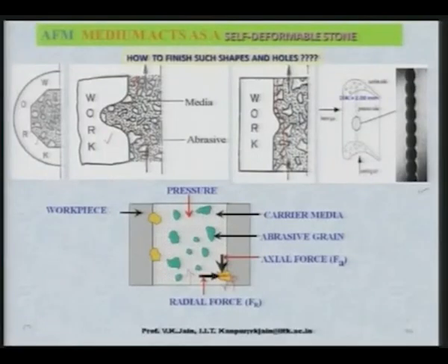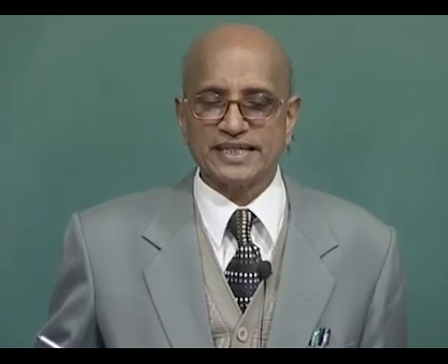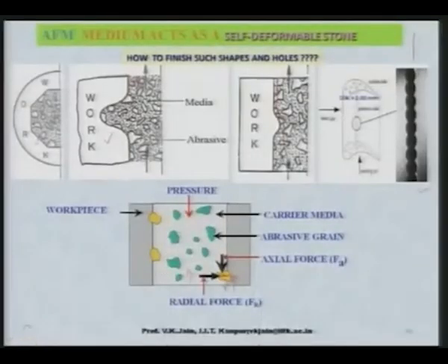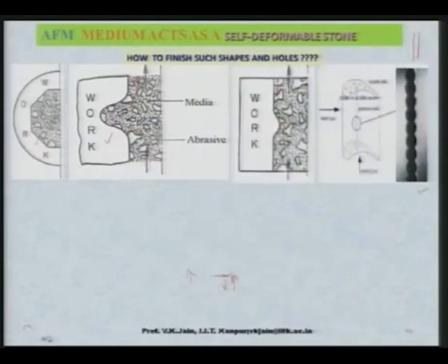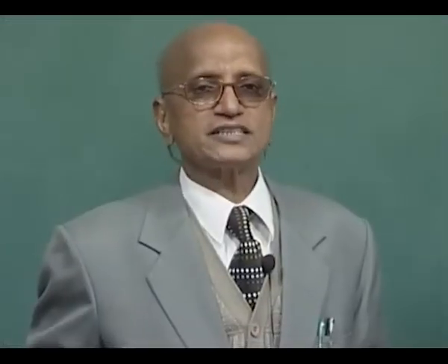These are the cooling holes in the turbine blade. Nowadays, the present day requirement of designers of the turbine blades is turbulated cooling holes rather than the straight sided cooling holes like this, which were made earlier. So, the question arises how to finish these cooling holes, because if these cooling holes have a very high surface finish, that is very low surface roughness value, then cooling will not be very effective.